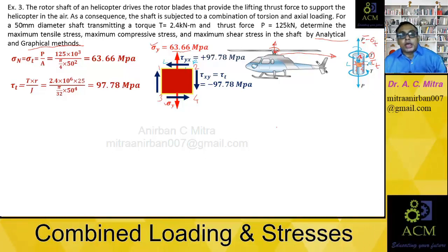Now once I have the direction of shear stress in one plane, on the opposite plane it will be exactly opposite to that top one. As in this plane it will be rotating in anti-clockwise direction, hence on the other xy plane it should be rotating in the clockwise direction. So tau xy direction is the clockwise direction only. According to the sign conventions, what we had explained in part 1, please refer to my part 1 for the directions of the shear stresses and the normal stress.